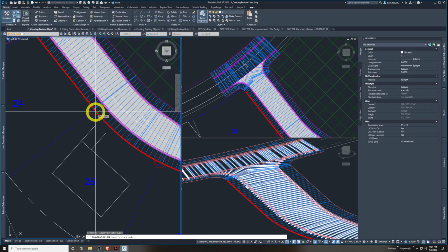So I'm going to go to the center of the red circle in the north corner. We'll start here, get the center highlighted, the center O-snap. Okay, that's picked. When I'm prompted now, it's always looking for an elevation. After we pick our horizontal location, it's looking for the vertical. You can specify you want it plucked from a surface. And you can also, if you hit enter, whatever's in the carets, understand if you just hit enter here, that would be accepted. So you get 0, which is oftentimes what you don't want. But in this case, we're going to accept it. Just hit enter.